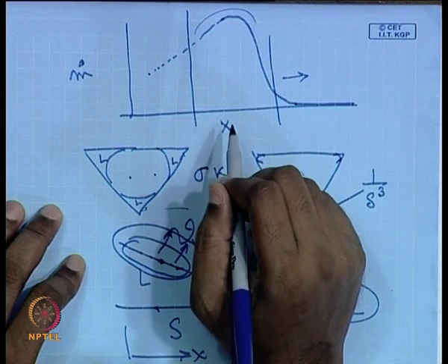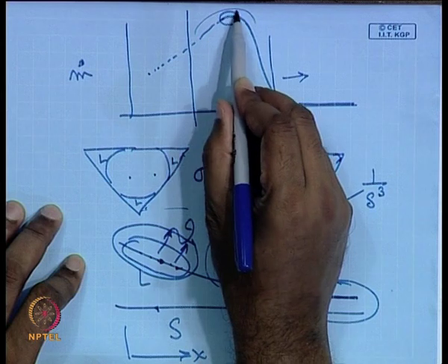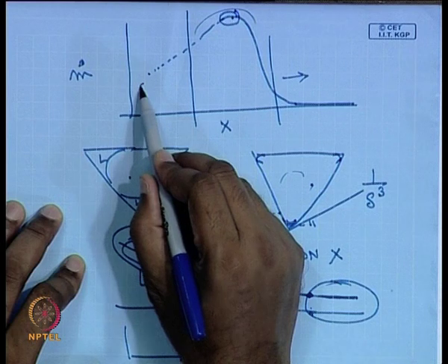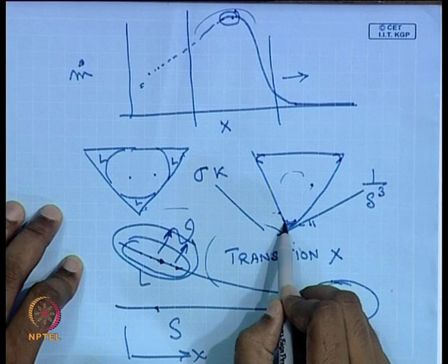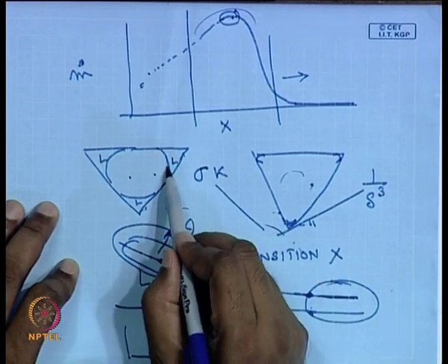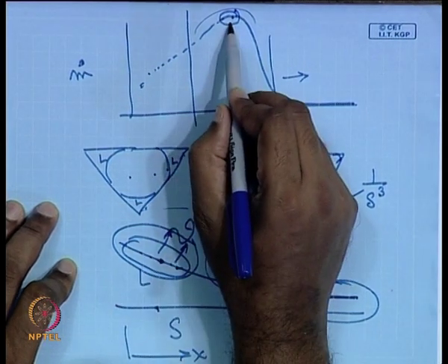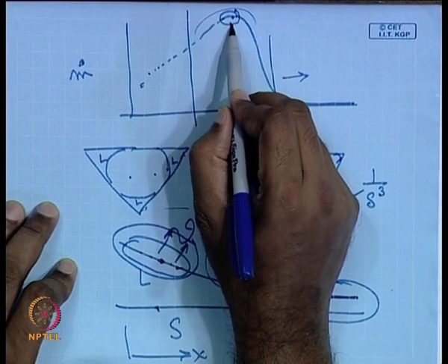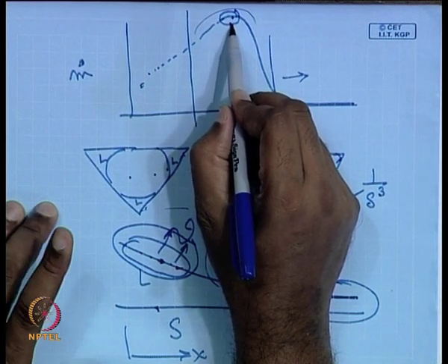The reason I am introducing this to you is to show that there exists a maximum which is orders of magnitude higher than the evaporation which is possible from the macro part of the meniscus. So, as I move towards thinner and thinner film, the area available for heat transfer, area available for phase change decreases, but the rate of evaporation will increase due to the less attractive long range intermolecular forces acting between the solid and the liquid molecules.